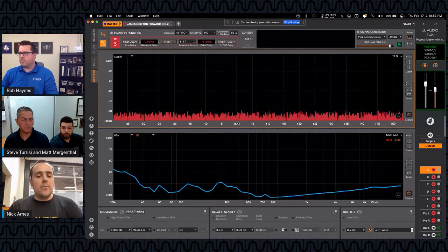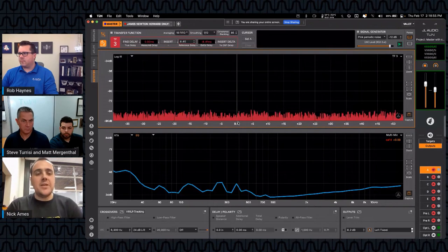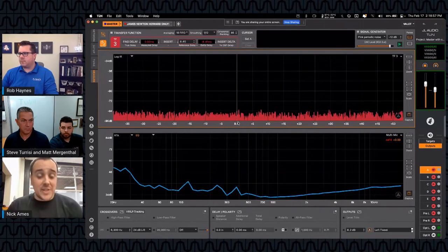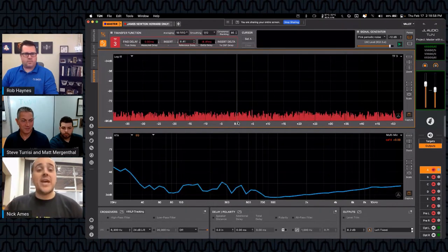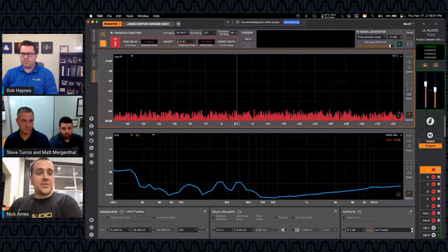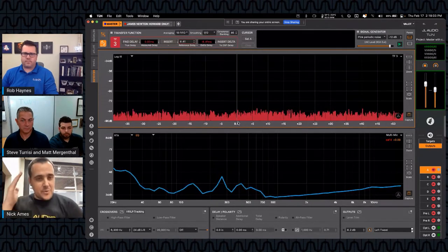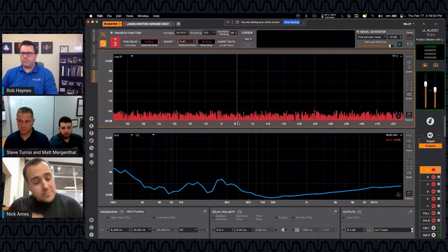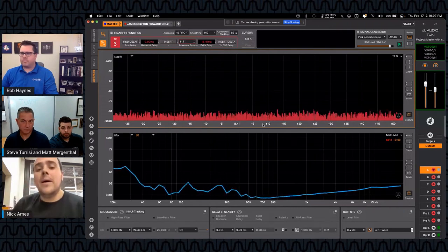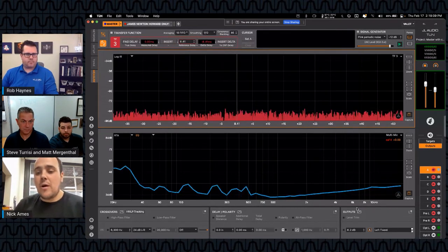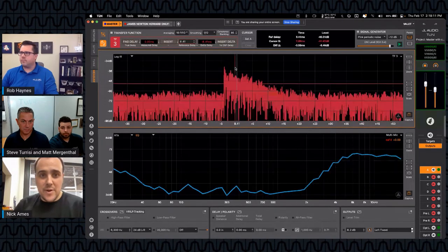And so now, since we have delay in the DSP, we don't have an ability, like you said, to advance time, but we can delay time. So we go to the latest arriving energy. We set that as our reference point, and then we can unmute them one by one and scoot them over in time until they arrive at that same point right there.